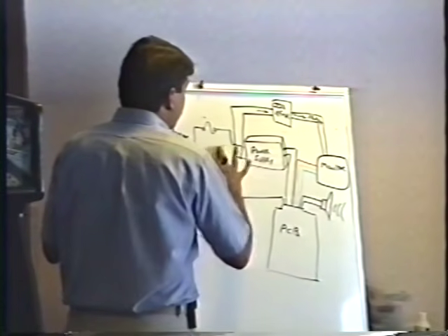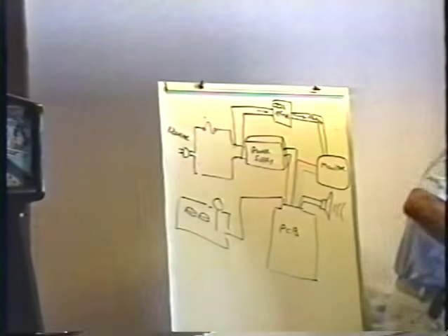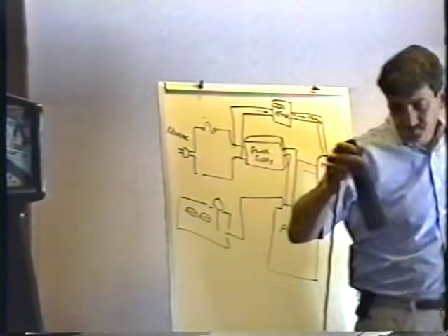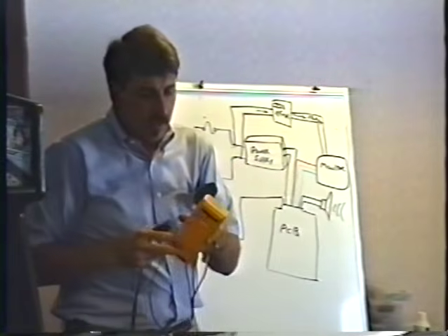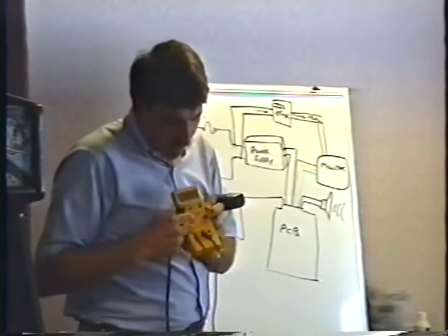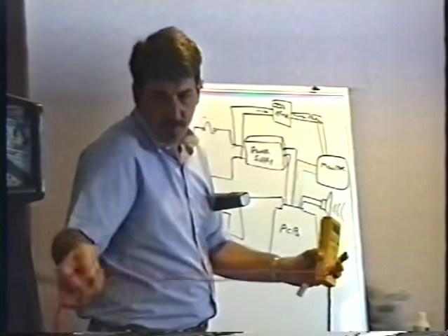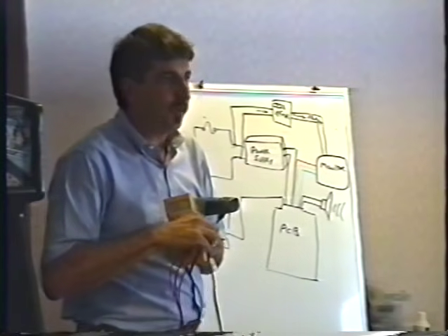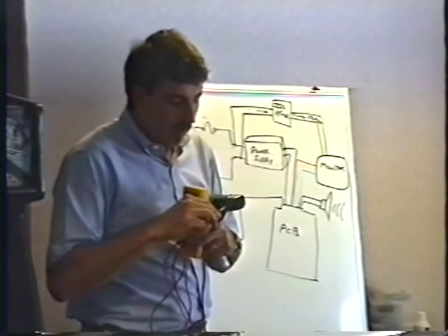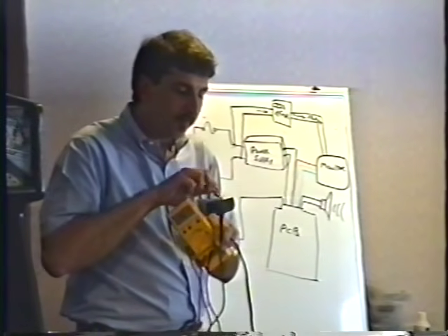With continuity. First of all, the first thing I did was this, and this is a really fast way that you can tell if the thing is hooked up or not. That is, if the cord is doing anything at all. I put my meter on the continuity beeper or on the ohm scale, whichever your meter happens to do, where it makes a beep. I put one meter lead on one of the prongs and one meter lead on the other prong.